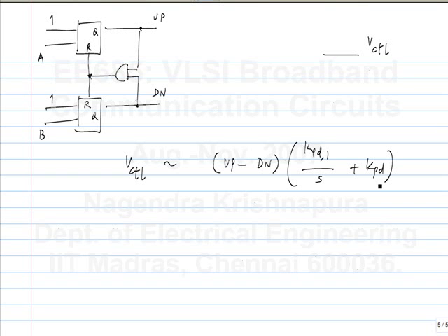How do we go about realizing this? No, it's up minus down, right? No, we don't further average it. So that's where we covered the non-ideality of the phase detector, right? So we said that we first imagined an ideal phase detector which gives you a DC based on the phase difference. With that we came up with the type 1 PLL. But then we also looked at a real PLL and said it has periodic disturbances in addition to the average. And those periodic disturbances created output spurious components which were too large in magnitude. Now in this also there will be that periodic disturbance in addition to the average. We simply have to go and figure out what the effect of that is on the output.